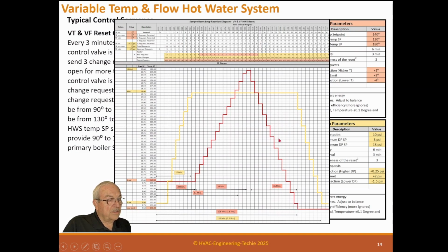So that this keeps us from doing any kind of wind-up. And wind-up is a mystery that can just drive you absolutely crazy. If you don't lock these together, if you don't have some mechanism in your sequence to make sure that the pump can go to minimum and the hot water go to maximum, which is possible, or vice versa, or both one way or the other, it can drive you absolutely crazy. But this actually prevents all that. These sequences give you good control over how quick you move, and this one, of course, is the temperature.